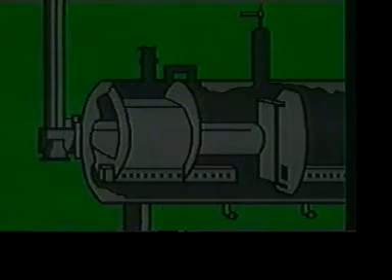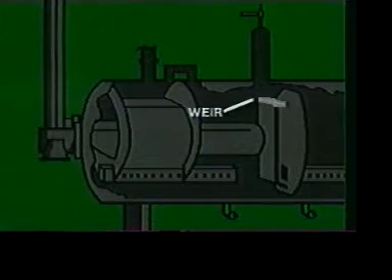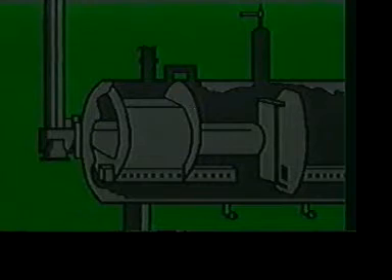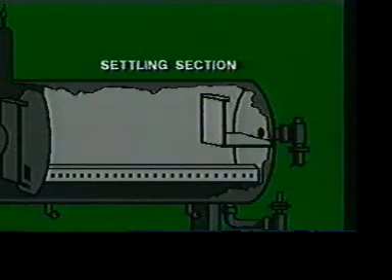When leaving the heating section, emulsion flows over a weir into the second chamber. A weir is a dam-like device which maintains fluid level in the treater. In the second chamber of the horizontal heater treater is the settling section, sometimes referred to as the coalescing section. A flow spreader receives emulsion from the first chamber and disperses it along the length of the settling section for more efficient separation of oil and water.